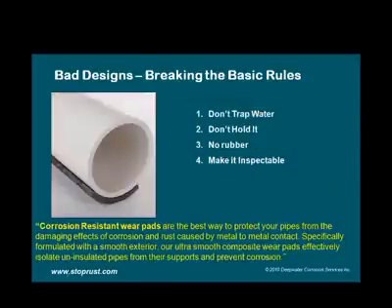The problem is that these do trap water, they do hold it, and they make it very, very hard to inspect. You can't see that whole area that's covered by the FRP pad. And this statement here at the bottom is directly off of the website of the company that manufactures those.